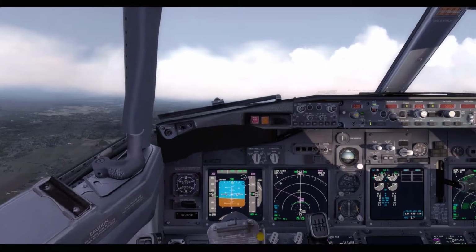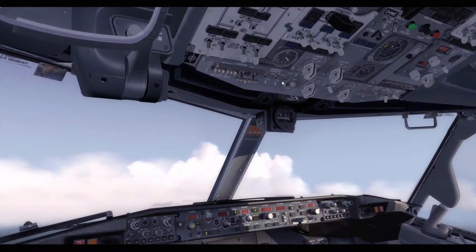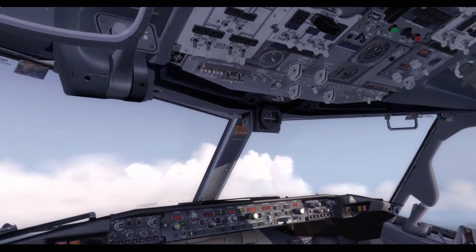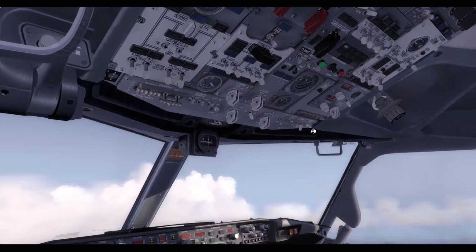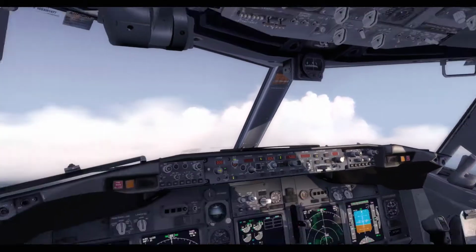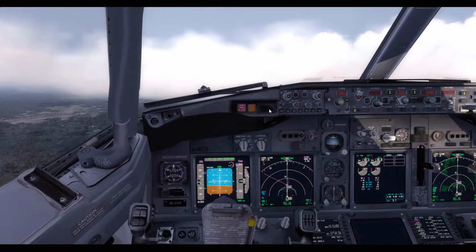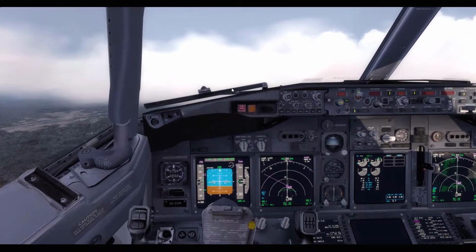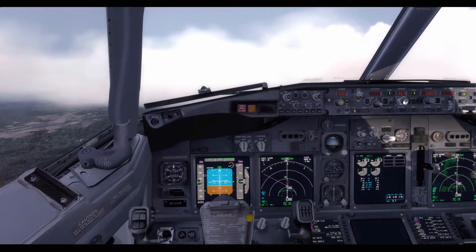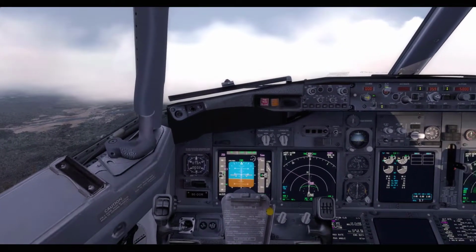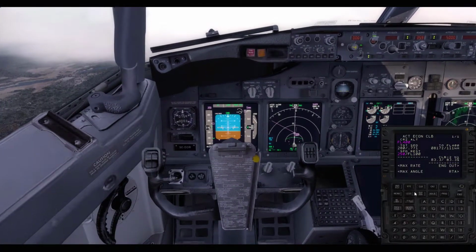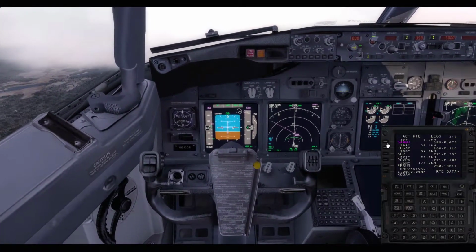Now we can put the gear lights off. Turn off and taxi lights off. Those can come back. And the wing light can come off as well. And once we are through those clouds, which I think are the reason why it is so bumpy, I'm gonna release the cabin crew. And what I will do as well is just to have a slight shortcut, go direct to COGAF.